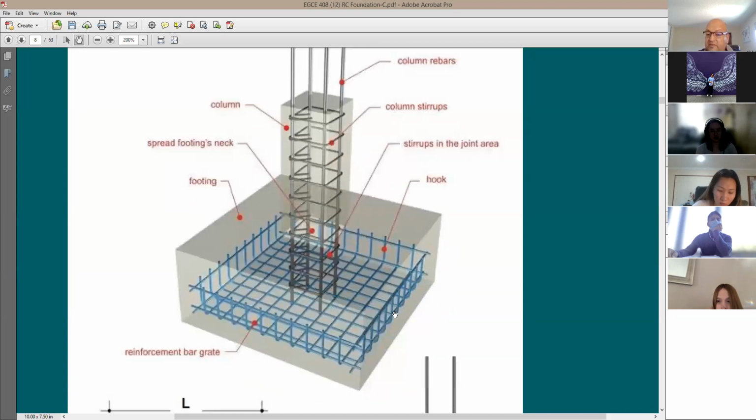Now, in the pad itself, we need to put some reinforcing. Now I'm thinking here, the pad pressure is going to be coming from the underside of it, going upwards. Meaning it's going to be pushing all sides of the footing except for the center of it. Because at the center you're going to have this column, and this column is not going to be going upward. So the footing here is going to start to bend up.